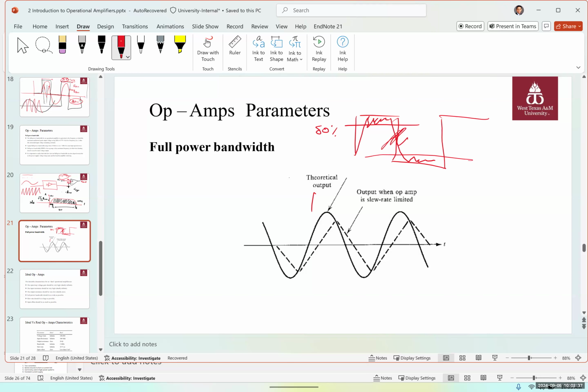So anything upper than that threshold would be accepted as a 1 or a signal. Okay, so yes, that's completely correct. We would always have slew rate and distortion, but if we retain like 80-90% of the signal, it's still acceptable. And that is determined by something that we call the SNR, signal to noise ratio, and that should be above a certain point. And that depends on the application.